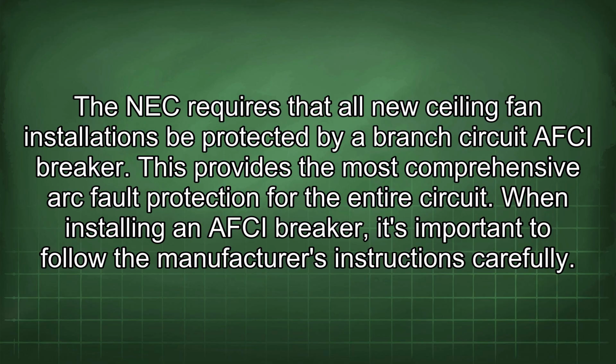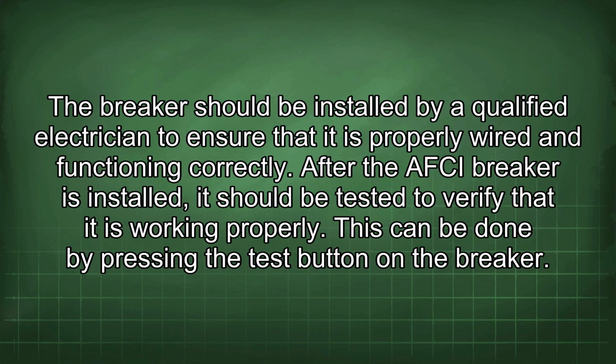The NEC requires that all new ceiling fan installations be protected by a branch circuit AFCI breaker. This provides the most comprehensive arc fault protection for the entire circuit. When installing an AFCI breaker, it's important to follow the manufacturer's instructions carefully. The breaker should be installed by a qualified electrician to ensure that it is properly wired and functioning correctly.